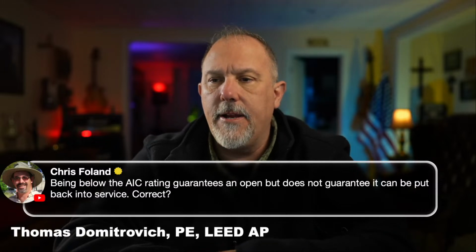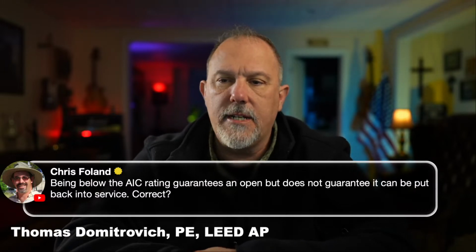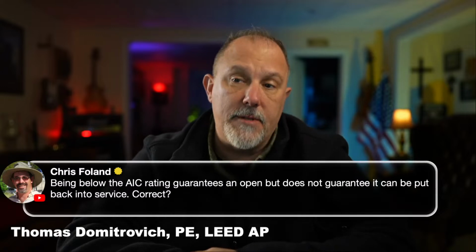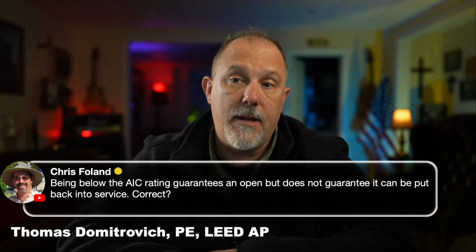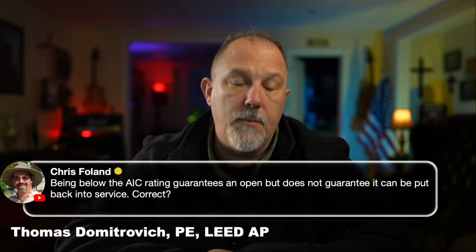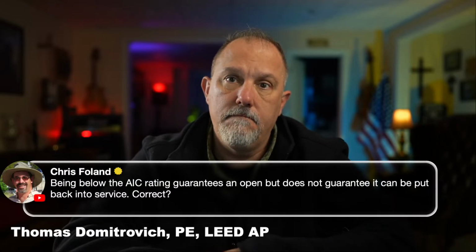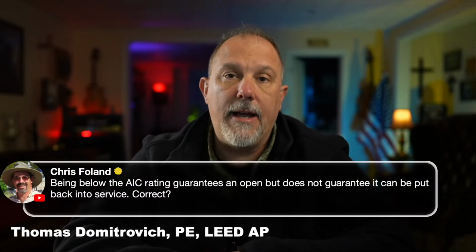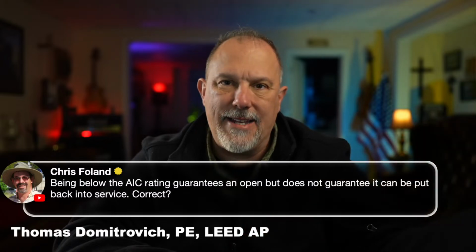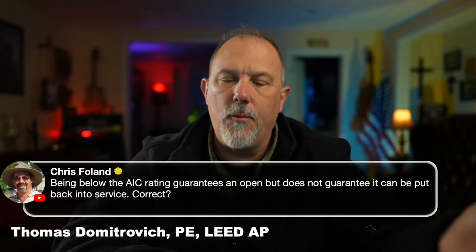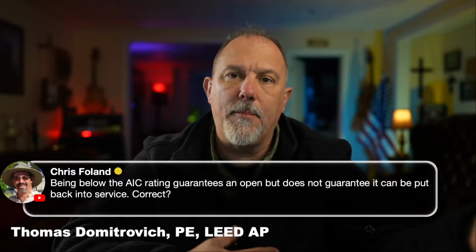Being below the AIC rating guarantees an open, but does not guarantee it can be put back into service, correct? That's what I would say, Chris. That's what I would say. I would put it through NEMA AB4. I can go through the standard and tell you how it's tested, what I feel comfortable with, and I can give you a comfort level on my personal opinion of things.